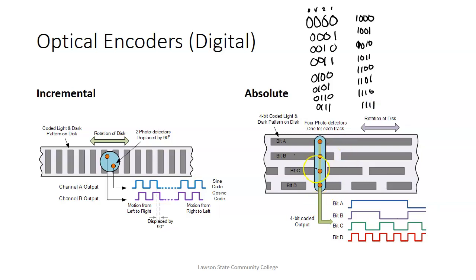So what we have is these photoelectric sensors. Basically what it does, it shoots a light beam, usually using an LED. And down over here it's got a receiver that every time the light hits it, it gives us a digital pulse. But these are actually going to give us a binary number depending on what lines up. So right now it looks like we've got this one on, this one on, this one on, and I can't see what's going on here. But if all of them were on, that would be a 15, which means we were at position 15.